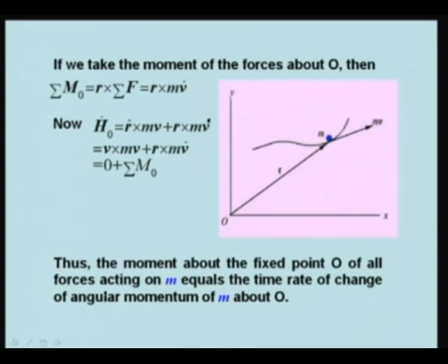We see that we have derived it like this: h dot O is equal to r cross m v dot, and if we have a system moving with a constant velocity, then its effect is not experienced. Means if it is valid for m v dot, it is also valid for m v plus c dot, and therefore this relation holds good for point O which is moving with a constant velocity.